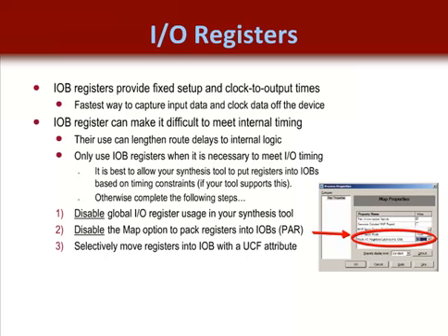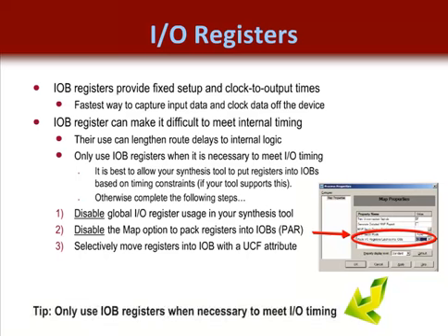Likewise, check your synthesis vendor's documentation if you want to make these attributes with your synthesis tool or your HDL. But however you choose to make specific registers put into the IOB, try to only use the IOB registers to help meet I/O timing.